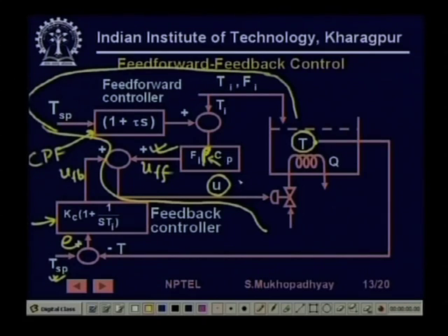So, what will happen is that the control input due to feed forward, only feed forward, will now be a little less. If it is a little less, then some control error will now build. That control error will be sensed by the feedback part and that will provide additional input. So, if due to modeling error this falls short, or becomes larger than required, then the corresponding compensating correction will be given by the feedback input and then the overall input will be just the right one.